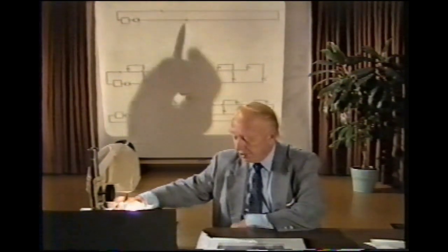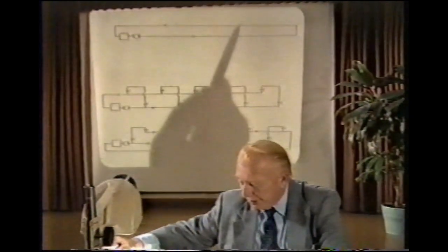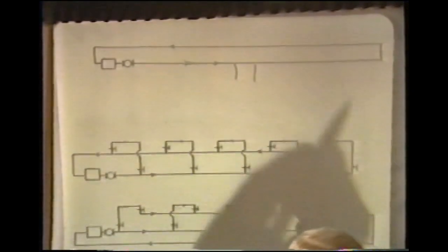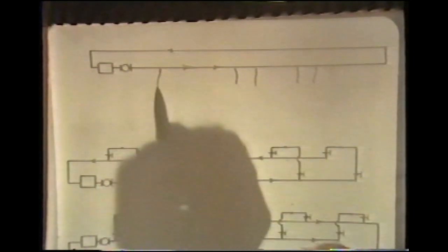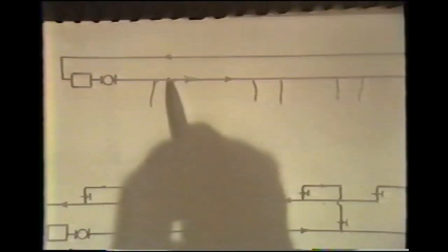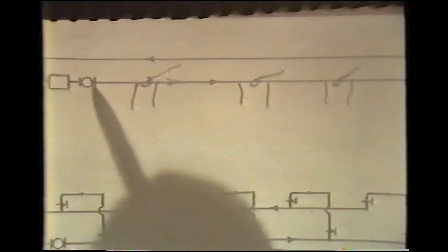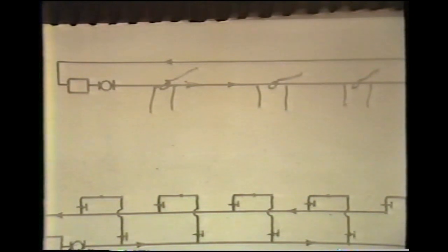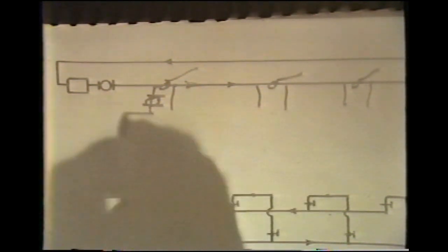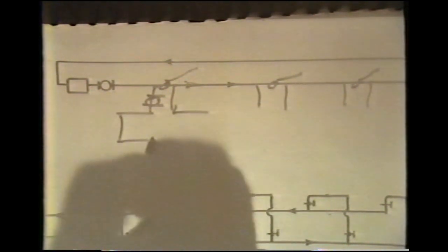And this illustrates, the top illustration shows a one-pipe distribution main. Now we can connect to that distribution main with primary-secondary takeoffs. But so long as the pressure drop in the common piping is relatively low, the primary pump need only concern itself with pumping of the primary distribution main itself. Pumping of the secondary circuits is, in this circumstance, taken care of by separate secondary pumps.